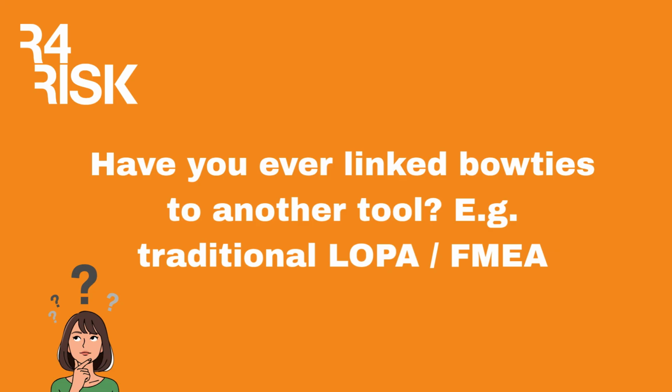Absolutely. Any kind of supporting information you can link a bow tie to. Again, it must be clear why you've made that decision on that cause, whether it's going to be a 1 in 10 year event based on such and such, or we're rejecting this cause because of such and such. Providing that kind of information is invaluable because you can then go back to either your LOPA, your FMEA, even LOPA guidelines.